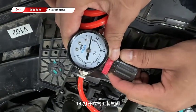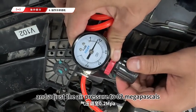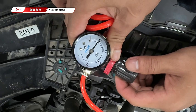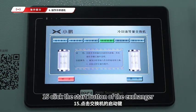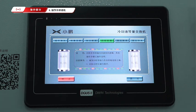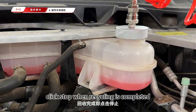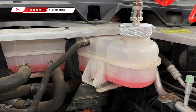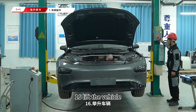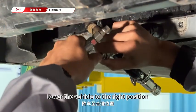Fourteenth, open the air blowing tool valve and adjust the air pressure to 0.2 megapascals. Fifteenth, click the Start button of the exchanger. Observe the state of the expansion tank. Click Stop when recycling is completed. Sixteenth, lift the vehicle. Replace the filling pipe. Lower the vehicle to the right position.